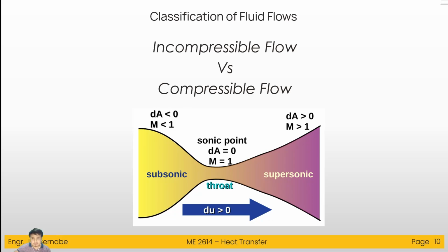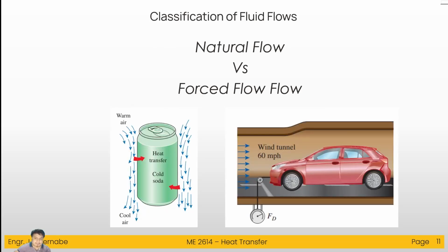Okay, now, we also have compressible and incompressible. So the difference between the two is compressible flow has a varying density. Realistically, density will vary. Buoyant force will also be at play in most of fluid mechanics. But in simpler cases, we assume that the fluid is incompressible, especially if it is water. So water is negligibly compressible. So we will just use incompressible. Compressible flow is much more complicated. Not really that much, but it is more complicated for analysis.